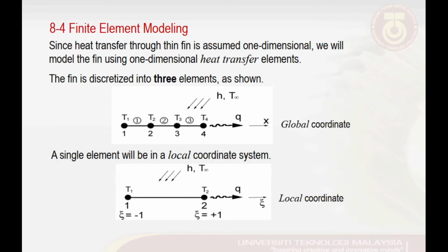And since the heat transfer through the thin fin is assumed to be one-dimensional, we will model the fin using one-dimensional heat transfer elements. In the first figure here, the fin is discretized into 3 elements and modeled in the global coordinate system.